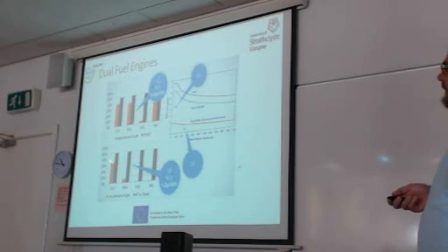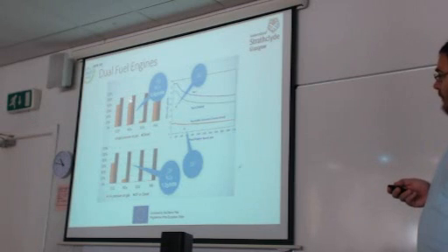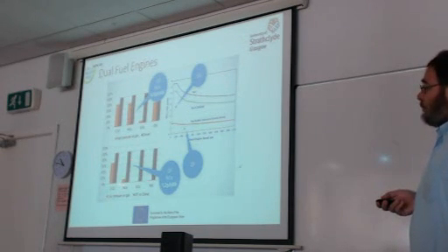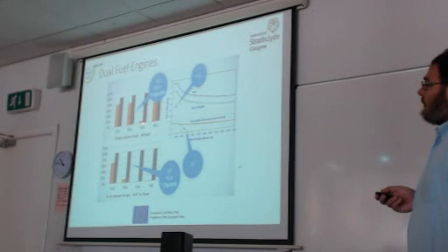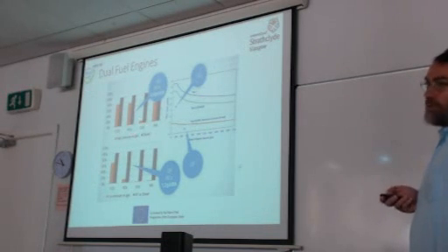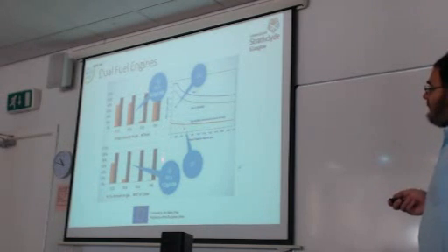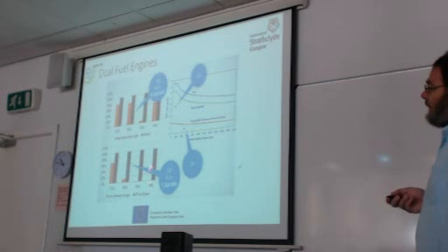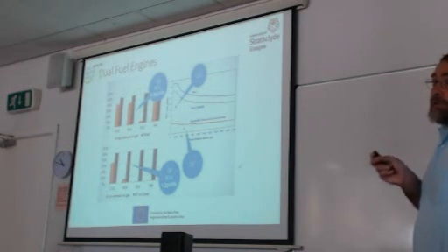So we have a decrease of CO2, which is attributed to the different carbon ratio between diesel or liquid fuel and gas fuel. This change is 12% for the case of gas diesel engine, and I think it's 30% for dual fuel engine. We have a small increase here. A huge decrease of NOx for the case of dual fuel engine. A large decrease of SOx, almost elimination of SOx in dual fuel engine. I think that depends on the amount of pilot fuel. If the pilot fuel is low sulfur fuel, then the decrease will be different.